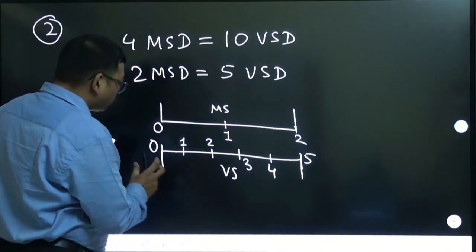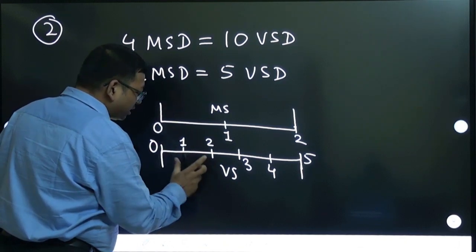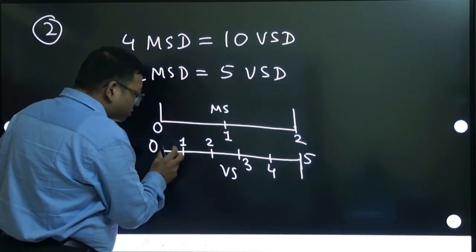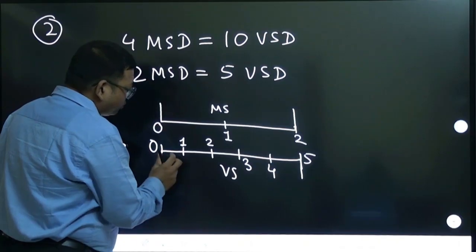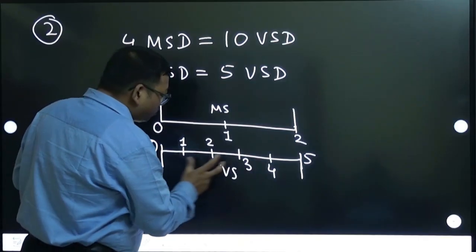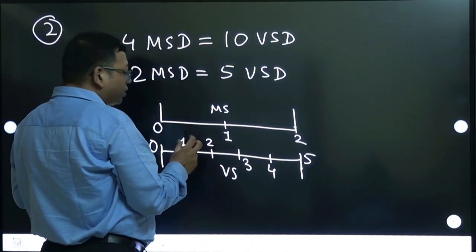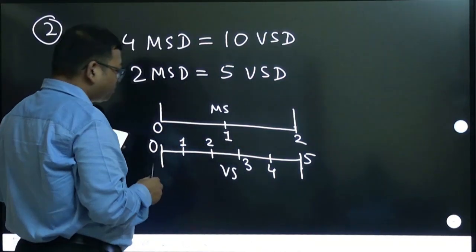Least count means, suppose I want to measure, so I need to displace this vernier scale a little bit, so that in between the jaws of the vernier caliper we can fit some object, right? So what is the minimum measurement? If I move a little bit, which division can coincide, that is what you need to see here.